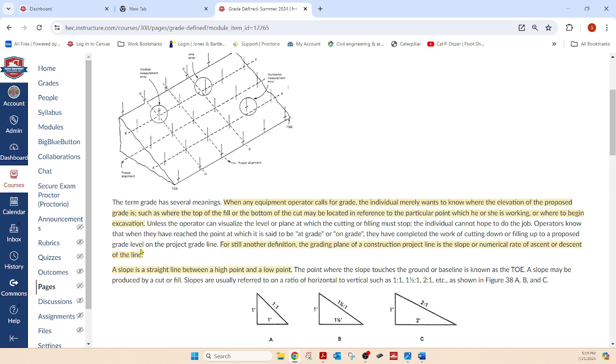It's just imperative. Next time you're driving down the interstate, if you're the passenger, look to the right and to the left, and you're going to notice some things. You're going to notice some diversions and some slopes, and you're going to notice some diversions in those slopes. It's taking that water where the contractor wants it to go, both while it's under construction and especially when it's finished and it starts raining. You do not want standing water on the road, right? So that's why roads have a crown.